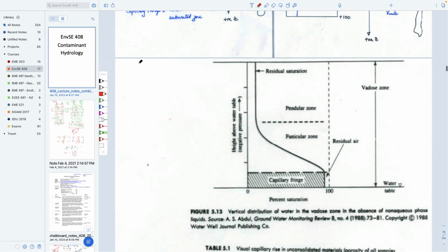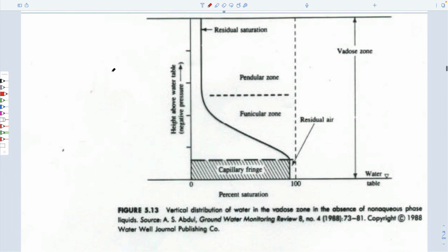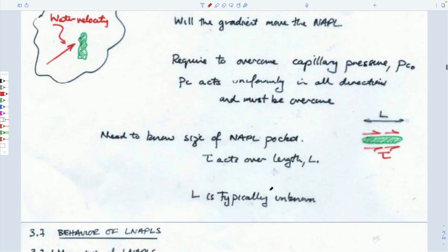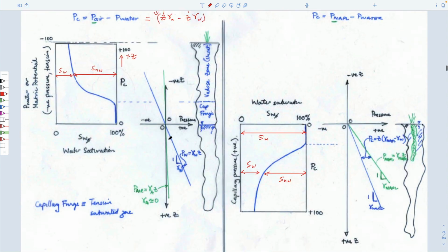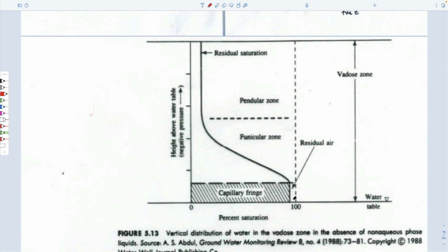And so I will rely on the figures that we have in our notes to do that, which are taken out of Fetter. And so this is for the zone which is immediately above the water table. So this would be this case here, right, for the capillary, the behavior in the capillary fringe. We've made the case that it takes a certain bubbling pressure that we have to overcome before we can get a bubble of air in there.